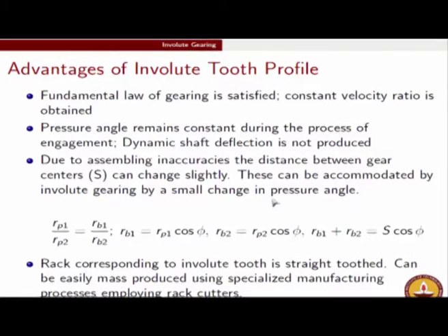So we know what a rack and pinion arrangement is. It turns out that the conjugate profile on the rack which meshes with the involute tooth on a gear is one with a straight tooth. So as this rack is meshing with a circular gear, it will cut out an involute gear naturally. This is very nicely shown in one animation on the Kinematics with Microstation channel on YouTube.